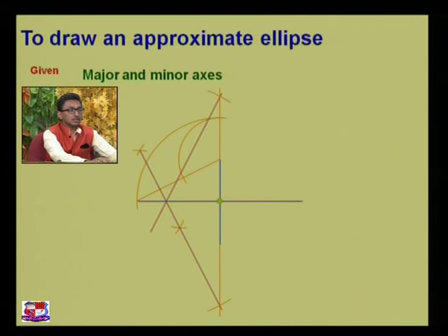We have joined both the points, this intersecting line as well as this arc. Similarly, on the opposite side, you have got this distance from this center to this much, so you can get it exactly opposite by just marking an arc. You have got a trapezoidal plane kind of surface.